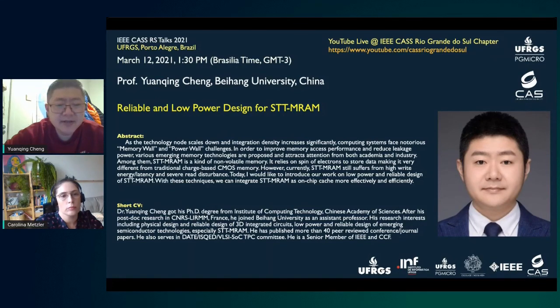But usually, the area of the cell structure is mostly determined by the MOS transistors, because we usually fabricate the MTJ between the metal layers that are above the transistor structure. And the MTJ itself is very small, sandwiched between the two metal layers.